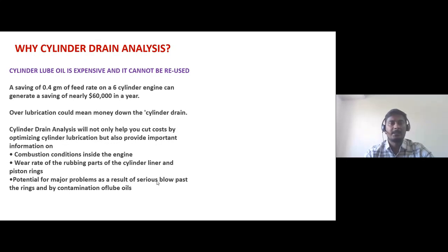Cylinder analysis will not only help you cut cost by optimizing cylinder lubrication, but also provide important information, like how your piston rings and liners are doing. If you need to take any corrective action, such as changing the rings or the liners, the drain analysis shows you. So it is helpful to you.